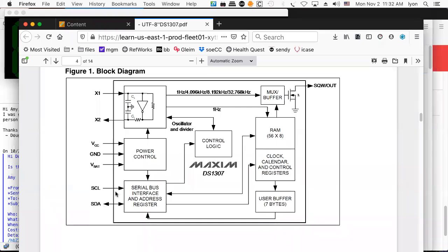The serial clock for the bus can't exceed the rate for any given chip that sits on the bus. And in fact, you don't want to just match the rate, because if you do that, you're really not giving yourself enough margin for error, especially if there's a little clock skew when you start to distribute the clock pulse.